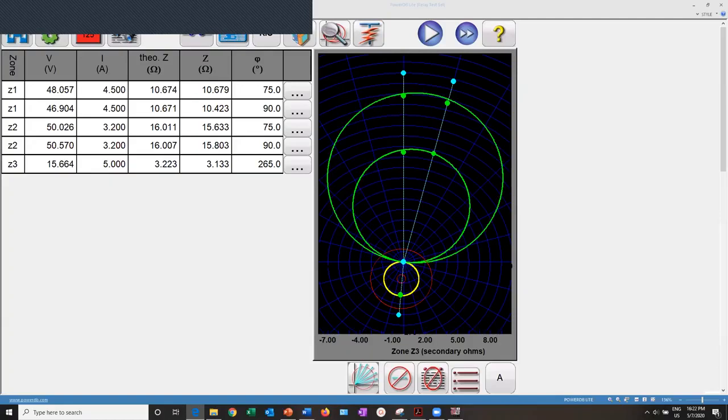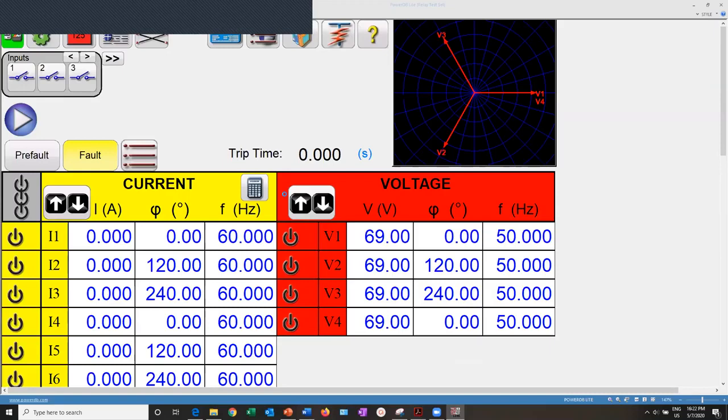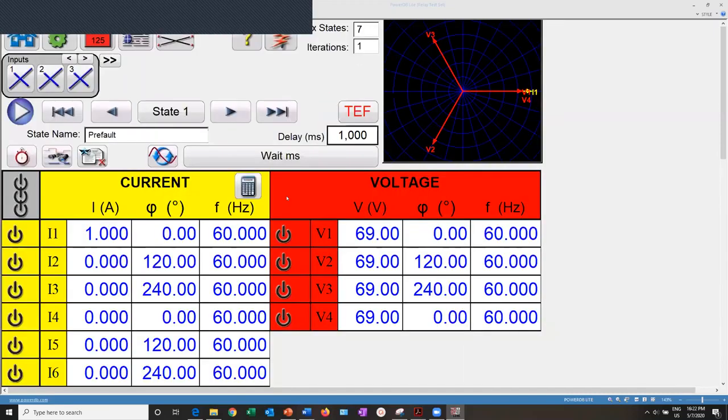And then you can set up the whole scenario in your state sequence to look for any kind of trip happening. When I say trip, it means any kind of output contact getting triggered, you can jump onto the next state, or you can stay at the same state. So there is a wide range of possibilities that you can do. And Mike Ditmore yesterday showed you how we can use a state sequencer. But if you have a specific question on your logic, you can get in touch with us, and we would be willing to help you out on that. Thank you.